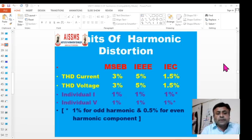Now we have seen about total harmonic distortion. Now there are individual limits also for individual harmonic components like second, third, fifth, and so forth. All the three statutory bodies have given the recommendation of a permissible limit of 1%.